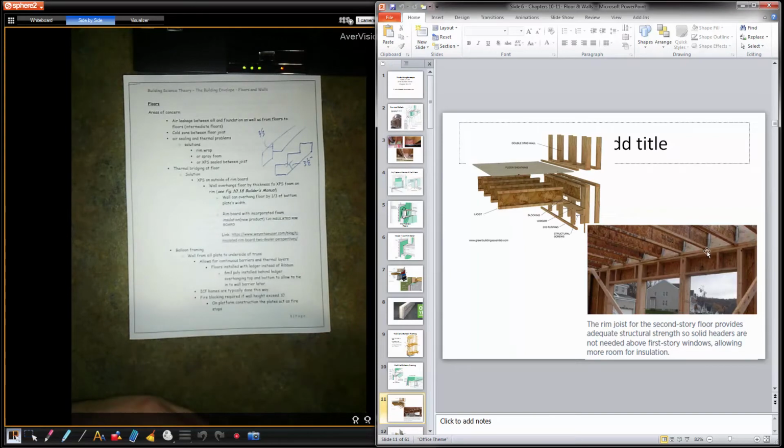So I could probably bring the insulation in an extra foot if I wanted to, as long as I wrap that properly to air seal it. With a wall, I'm limited to that 5.5 inch cavity. Well, I could put foam on the outside as well, but imagine if I can over insulate that floor system, I can then get maybe my R24 easily, if not trying to exceed that to make sure that it's warm. Okay, so that's a pretty good idea on a wall with lots of windows. Eliminate the lintels, have the floor carry the weight through all of the studs.